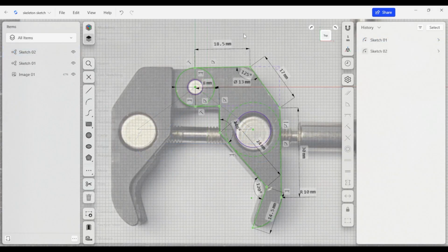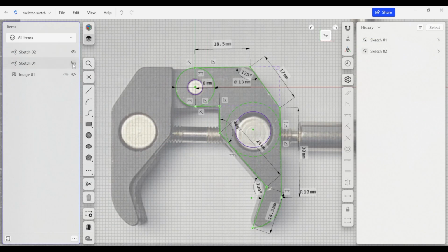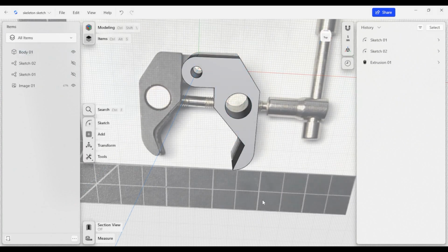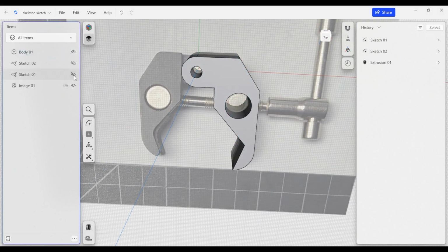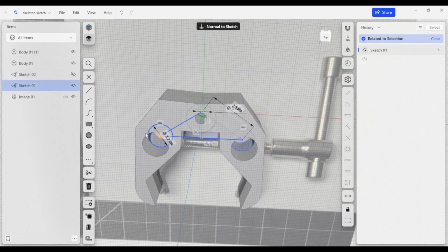In other CAD software, assemblies are traditionally used to create the relationship between components. And we'll create those mechanical relationships within Shaper 3D using a set of parametric sketches called driving sketches. Sometimes these are also called skeleton sketches.